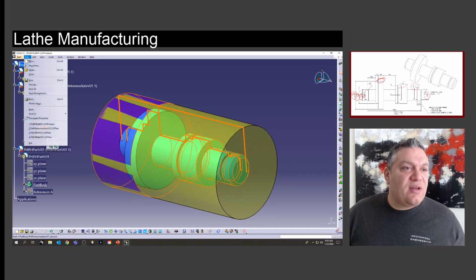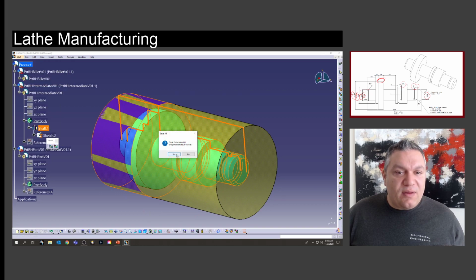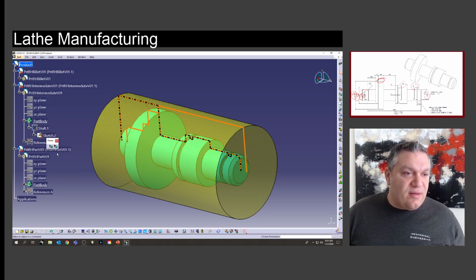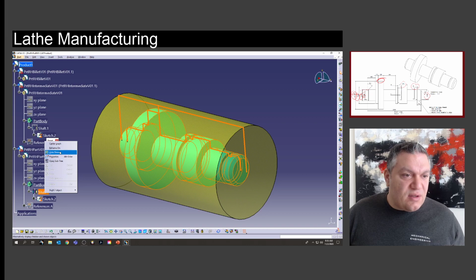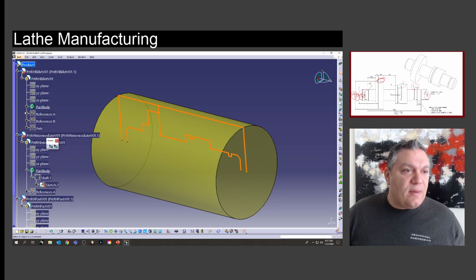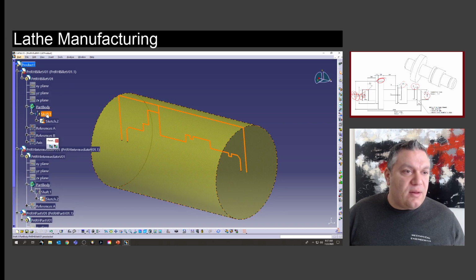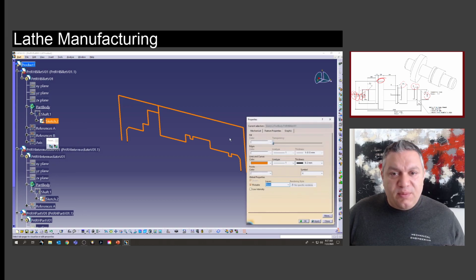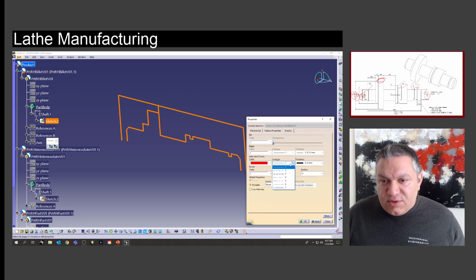in the manufacturing. I'm going to save all, yes, and I'm going to hide the shafts now because we don't really need them, we just need the references. Hide, and in here we're going to hide. What I'm going to do is put the original billet in red, and let's change the type to something dashed.